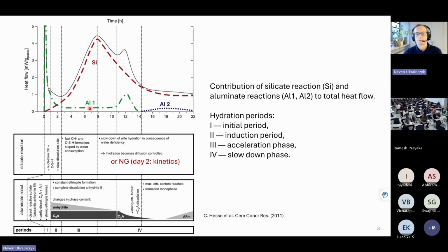But the sulfate actually also adsorbs on the cement clinker and also blocks the aluminates. And that's why we don't have any more reaction of aluminates. But the moment you deplete the sulfate, that's why it's very important to have the optimal dosage of sulfates. When you deplete the sulfate in the solution, or also the gypsum, which is dissolving, so when you deplete the sulfate, then you start again the aluminate reaction, because the sulfates then desorb from the cement surface, from the C3A